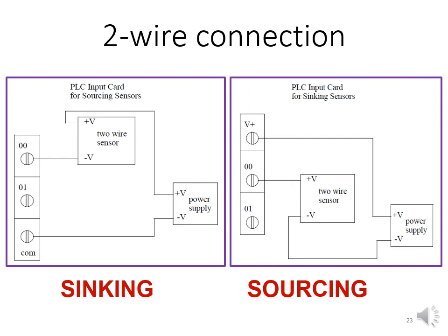For the case of a sourcing sensor, the arguments are the same. The difference is that for a sourcing sensor, the collector terminal on the output stage of the sensor is joined together with the negative terminal of the sensor to produce a single terminal in the diagram labeled as V-. That terminal is connected to the power supply negative point.